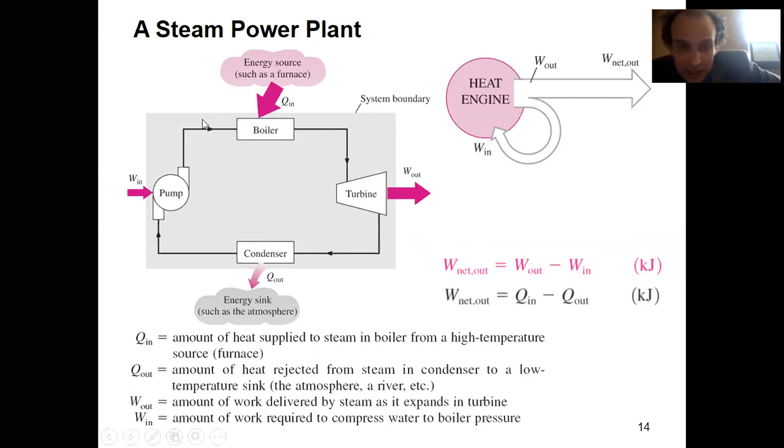But the key point, these two devices, boiler and turbine, are crucial, but they do not make up everything. Because what happens next? Next, you should have some kind of condenser. What happens in the condenser? It condenses, so your latent energy goes to the environment. So you lose some heat here. And then you have a pump which goes back, compresses the substance from outlet here to here, and then you boil it again. Definitely, in the pump you deposit work, so this work is negative from the point of view of the system, but work of the turbine is positive.